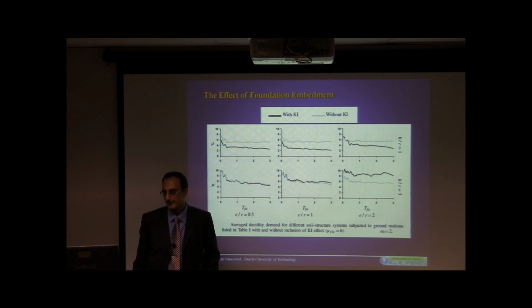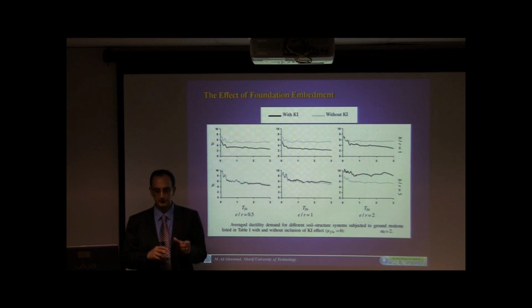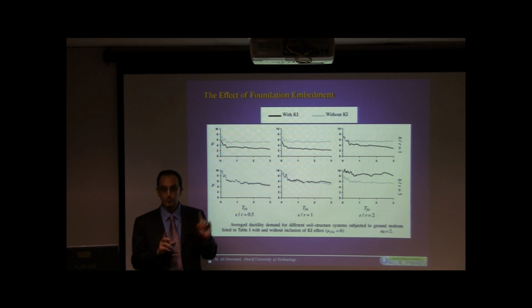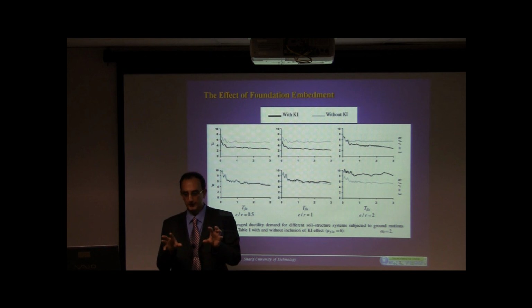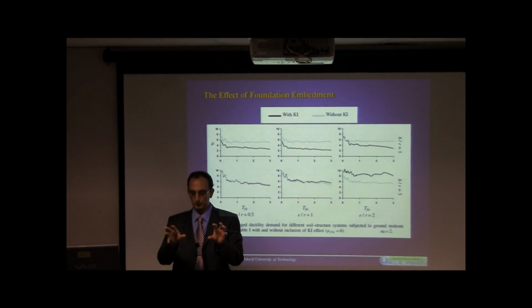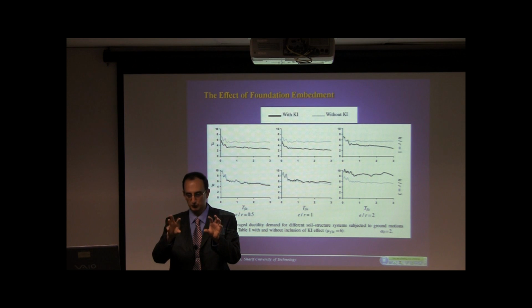Not from inertial, from the kinematic interaction. Of course, both systems are free to rotate. So both of the systems, even without kinematic interaction, have rocking motion in response, which results from the flexibility of the soil.